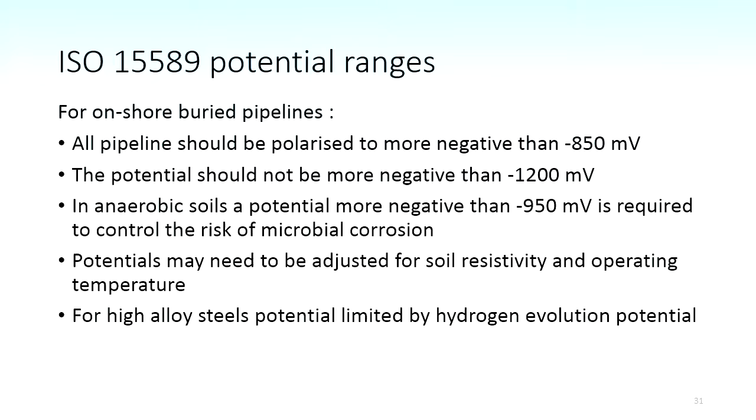So generally, as a general guideline, the potentials lie between -850 and -1200 millivolts versus the copper sulfate.